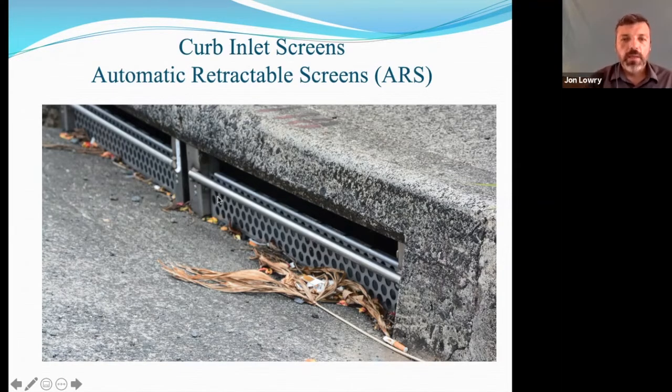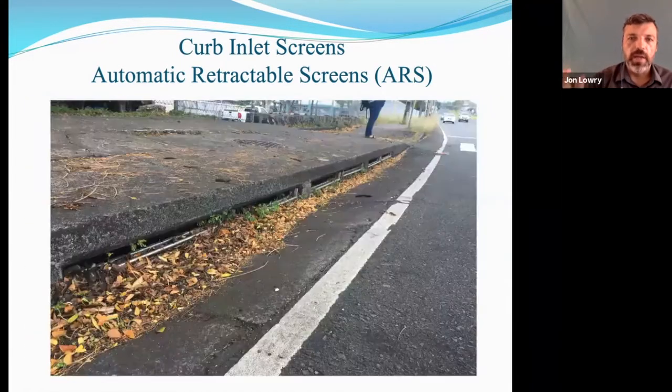One of the issues that we have noticed, I'll zoom ahead here, is when we do get these organics and litter built up, then it often will hinder the automatic unlocking mechanism from working properly. So as contractors, during your maintenance period, we're looking for you to give us information on how frequently different screen guards in different areas need to be cleaned in order to keep them operational and functioning properly.